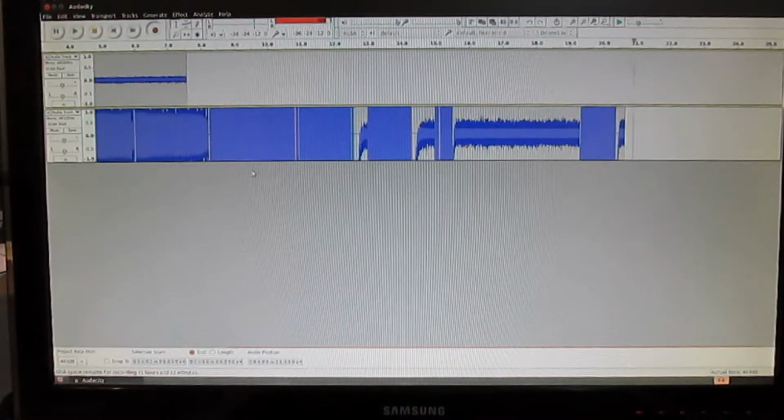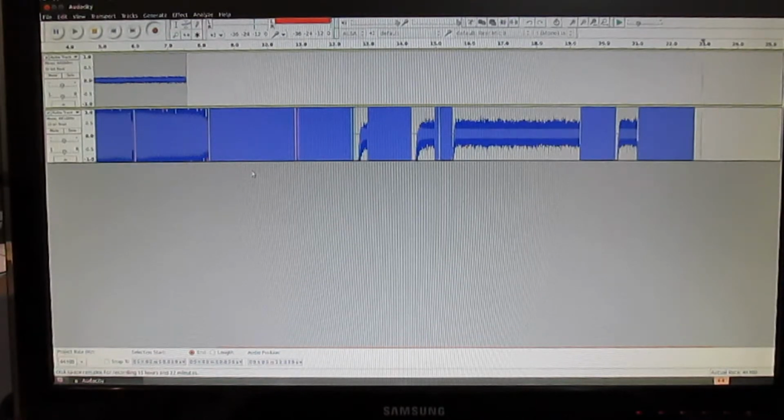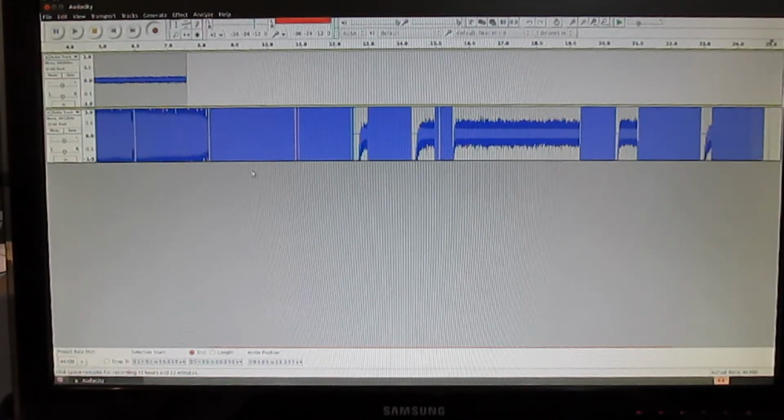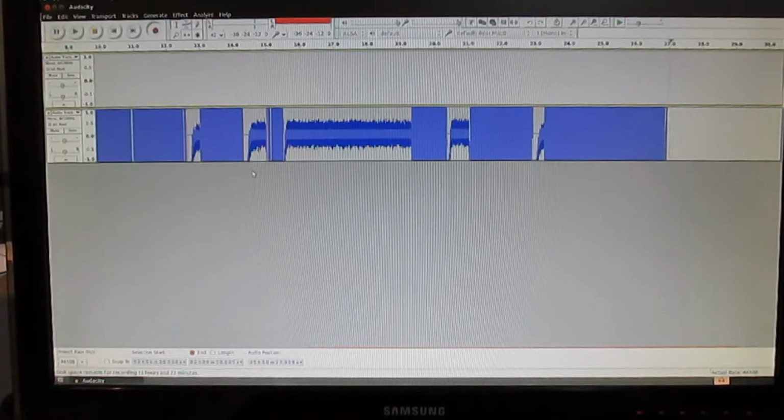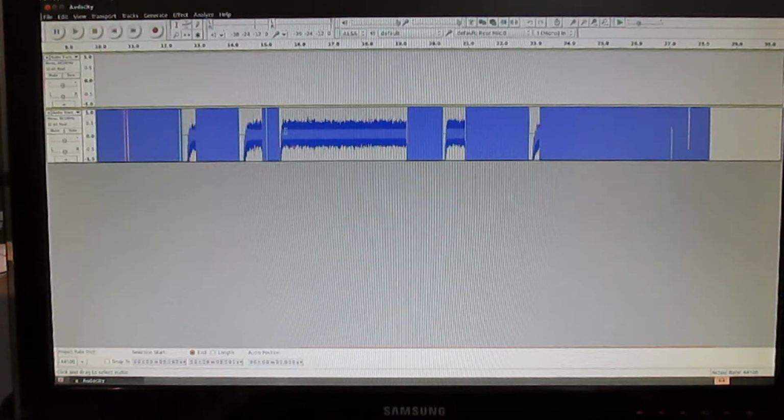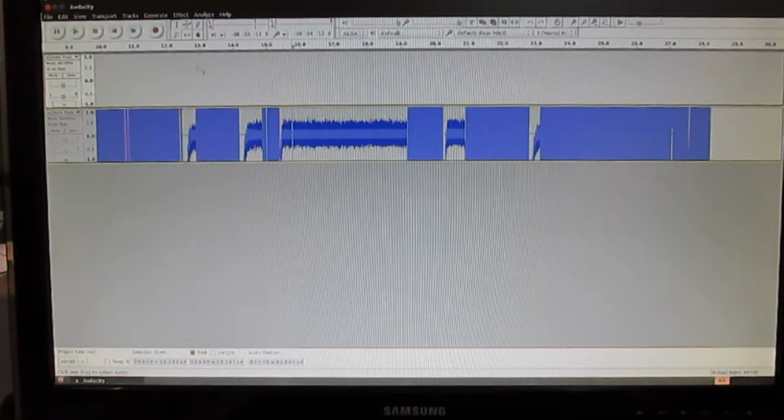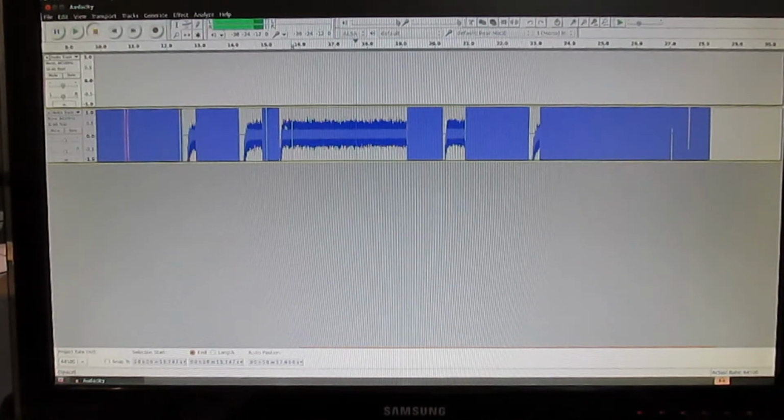Kind of hard to get it just right. I sort of have to hold on to these resistors to get good connections. Otherwise I just get a bunch of 60 hertz on there. But I think this section right here is good data. Let's take a listen to that. Yep, that's all white noise.